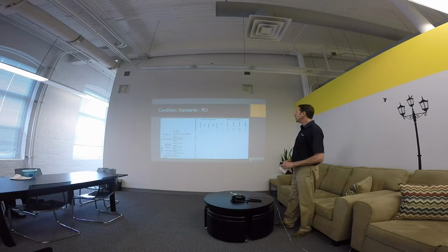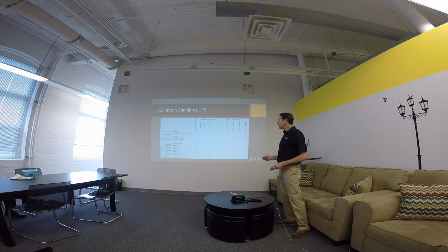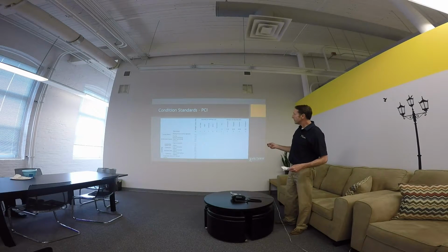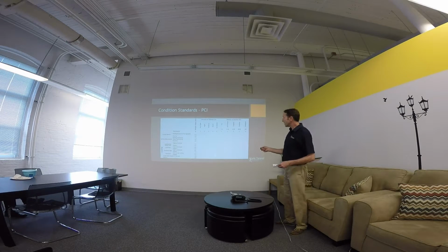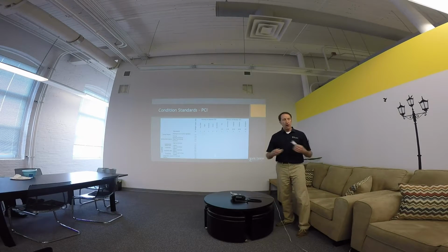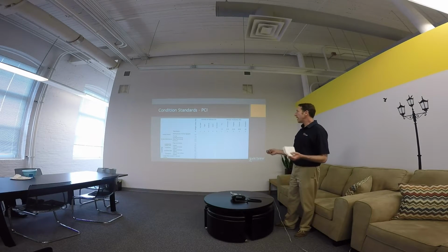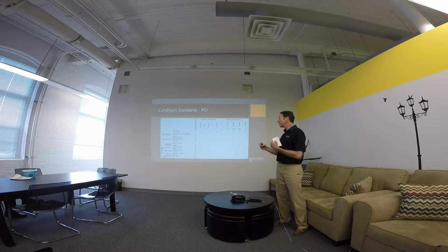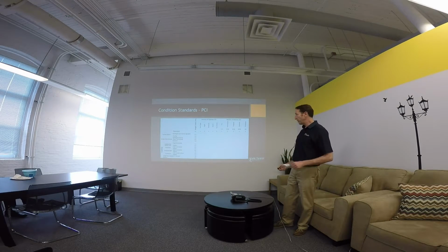Here's a typical form where they'll measure the deducts or the defects, and there's the severity up here. So you'll have raveling, flushing, rippling. You'll have the cracks here. You'll have these distresses rated here, and then the density of distress, which is actually how often it occurs. Certain items are also more important, so they'll get a weight as well, 3, 1, 1.5, and such. Those will be totaled up and deducted from the 100.